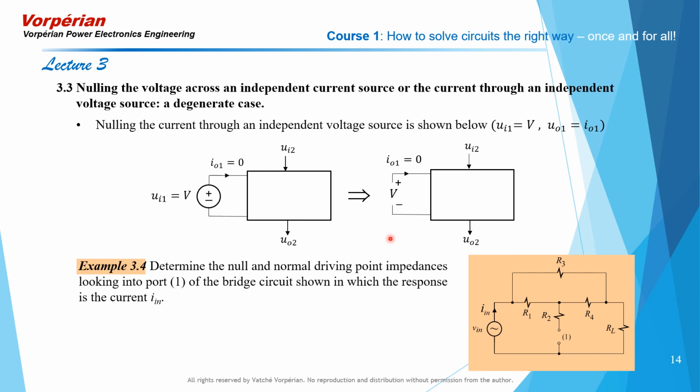You find out that the current that you will compute through the first resistor R1 will be the same as if you had two resistors in there or two voltage sources, the first one V1 and the second one, replacing R2 with a value equal to what you get from the first voltage division, input voltage V times R2 over R1 plus R2. You put that voltage source there, you get the same current flowing in the branch. And that's the substitution theorem.